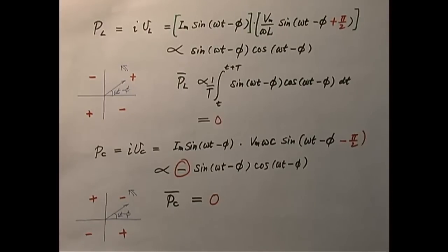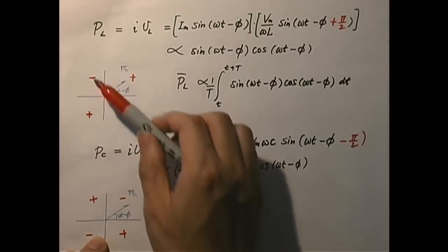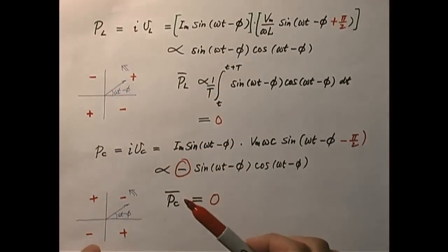But that EMF doesn't have to feed energy into the inductor and capacitor over one cycle. Rather, it only needs to feed energy to the resistor. And just like before, the inductor and capacitor never consume any energy as a whole over one entire cycle. Rather, they just temporarily store energy and then give energy back a time later.